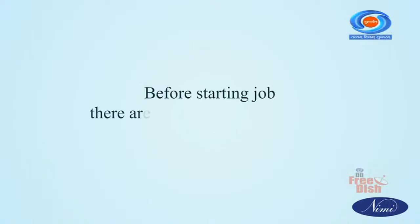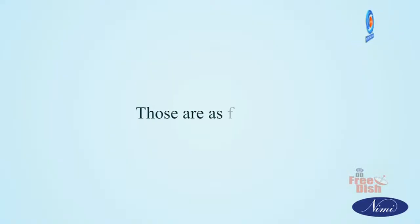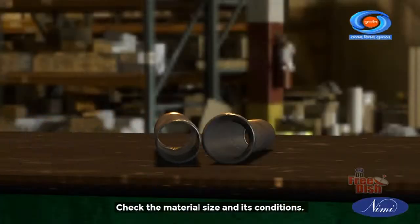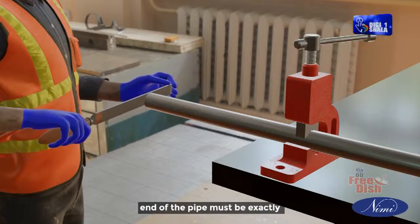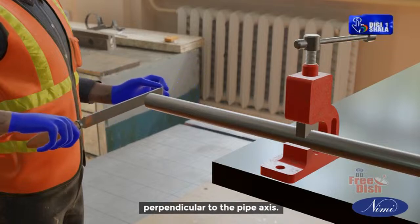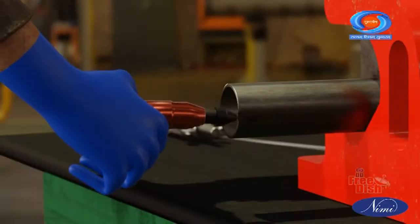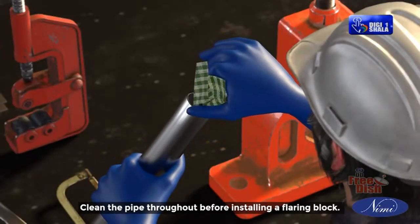Before starting the job, there are some preliminary checks to be made. Those are as follows. Check the material size and its condition. File and check that the end of the pipe must be exactly perpendicular to the pipe axis. Slightly deburr the inside and outside edge of the pipe. Clean the pipe throughout before installing a flaring block.